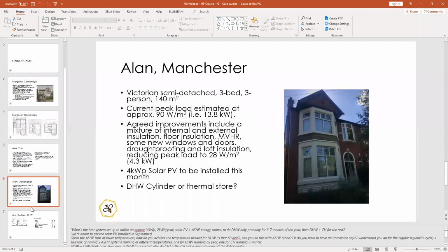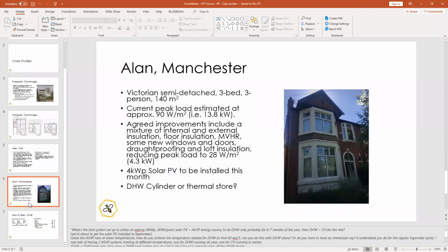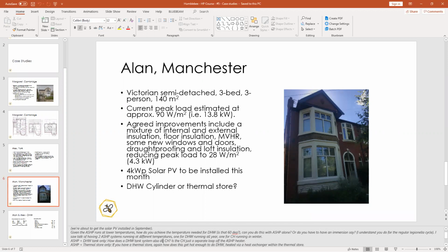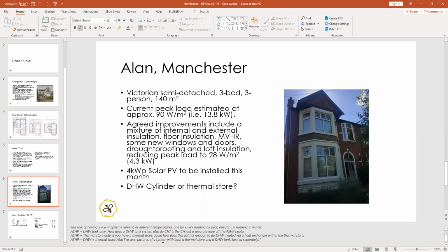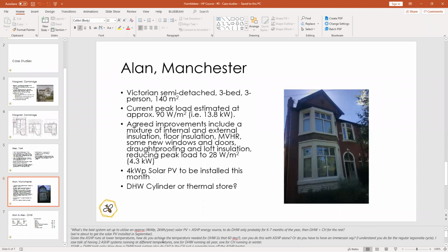I would suggest he perhaps changes his tariff, if he hasn't already, and then he could maybe load the hot water tank to a high temperature during the night. Yeah, I did suggest that to the installer, and I also said I was worried about cycling and that being inefficient, but he just kept banging on about the hot water and that people complain about not having enough hot water. But that is boiler thinking, I'm afraid.